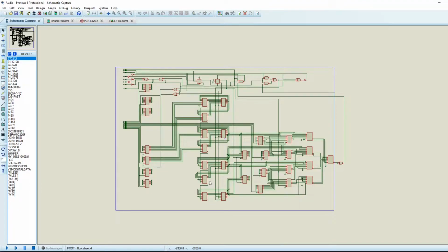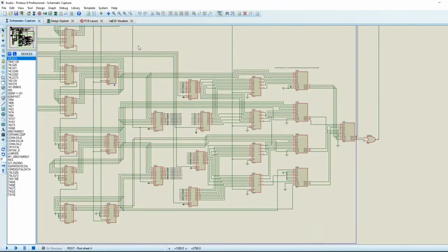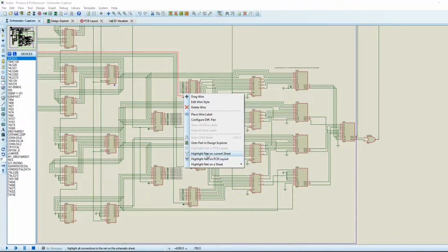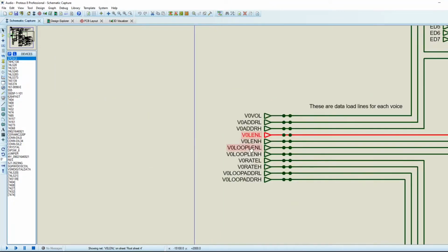So it's quite a large internal state that it's maintaining. Now don't forget that the rate value has an accuracy of 12 bits. So we're only doing a comparison with the last bits of the internal counter value, because we shift it down in the Java code before doing the comparison with the sample length or the sample loop length. That's why we only have a smaller number of comparators, taking the values in here. These latches here, of course, come from, I'll go back, you can see here, the length or the loop length latches.